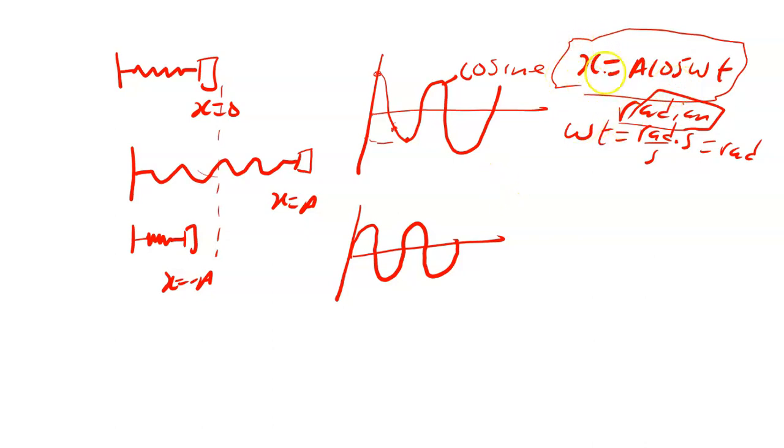So this is displacement. The moment you differentiate displacement with respect to time, you are going to have velocity. So dx/dt, the reason why I'm saying dx/dt is the function is x, which is depending on time. So dx/dt will be equal to our velocity, which is equal to the derivative of omega t, which is just omega, so we multiply by what is in front there. Then derivative of cosine is a negative sine, that's why we have a negative.